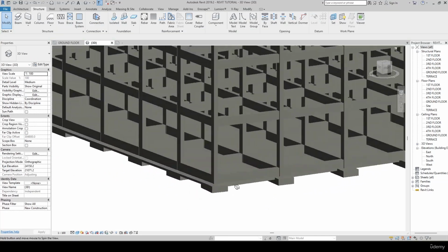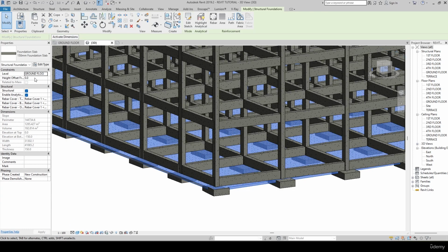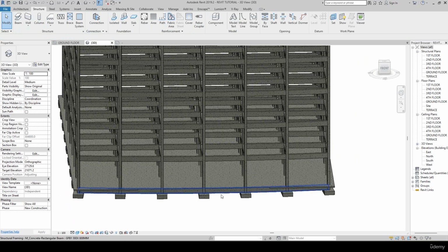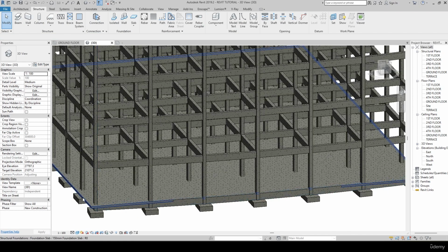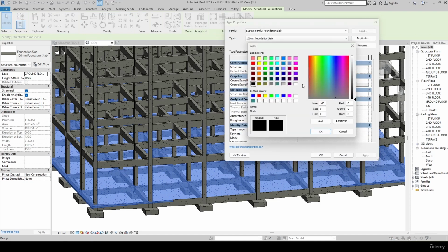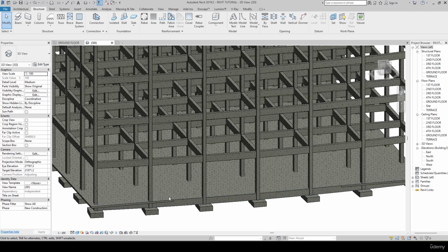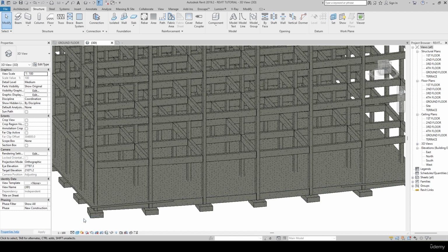But basically the slab has to come above this. Let me go here. I'll give the offset as 600 mm. Now it comes to the top. See, the grade slab has now been added. So maybe for understanding, let me go here. I edit this. As of now it's block. Maybe I'll give some color to this. Let me add this. Okay, for my ease of understanding, you will find this. I'll go here, I'll use consistency color. No, I'll keep the shaded.